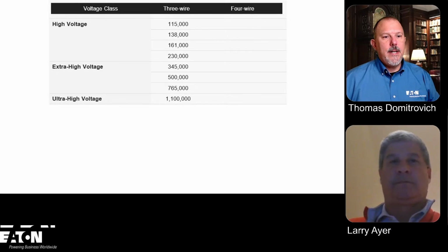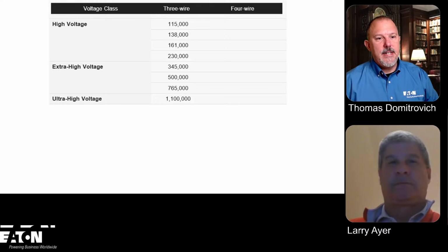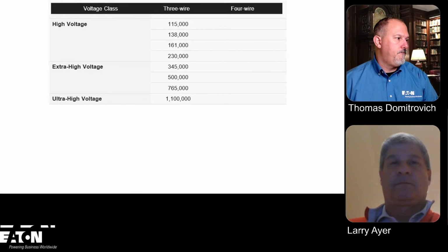Why do we not have a table for 75 degree on medium voltage? Is the 75 a bottleneck? So Juan Delgado is asking about the 75 degree, and in reality, the equipment is all 100% rated. It's all rated so you don't have to do the 75. 75 is associated with heat and low voltage equipment.